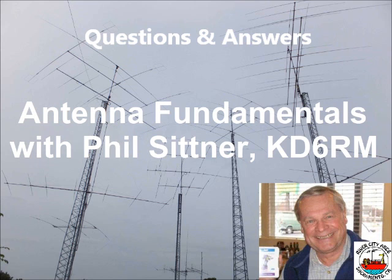Well, most beam antennas, for example, are designed to work into a 50 ohm coaxial cable. If you deal with UHF collinear arrays, they're designed for a 50 ohm system. By the way, if you go into cable TV stuff, what's that impedance? 75 ohms. But there's more than one way to skin a cat. You can build what's called an inverted V antenna. When you take the dipole antenna and drop the ends down, it'll get very close to 50 ohms.